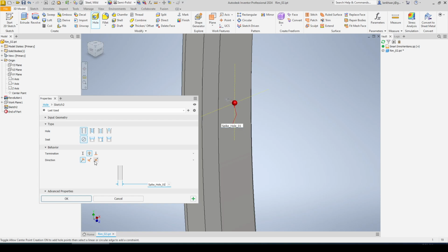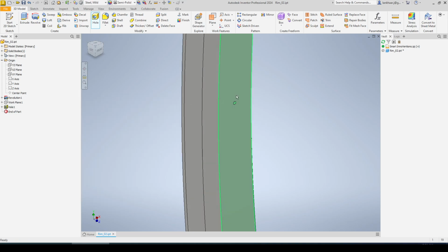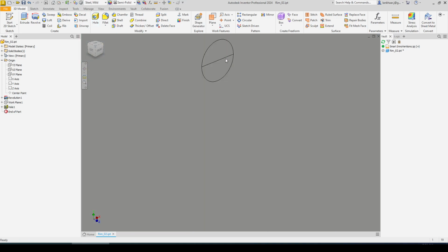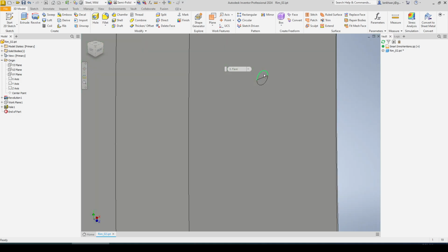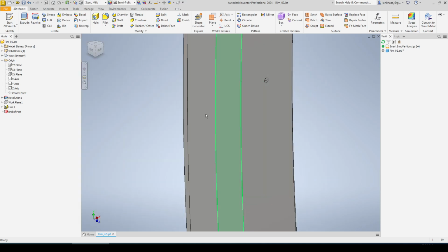And I'm going to use symmetric because now the hole goes in both sides, because on this side of the hole, the material is a little bit bended. If I don't do it, I'll show you, then you don't see the hole. You see only a little bit. You see there's a sort of an envelope, like a slot in it, but the hole is there.